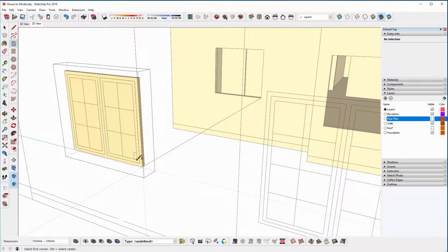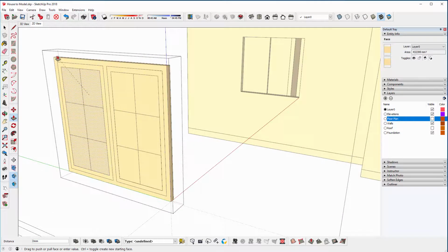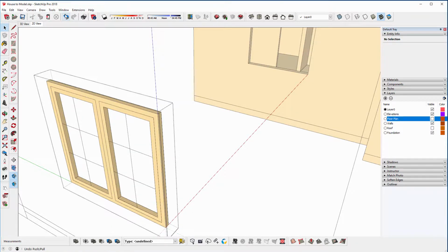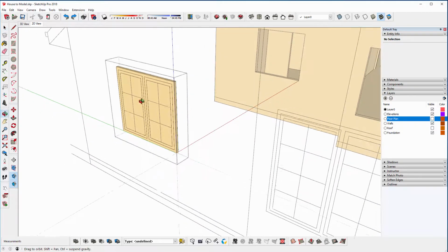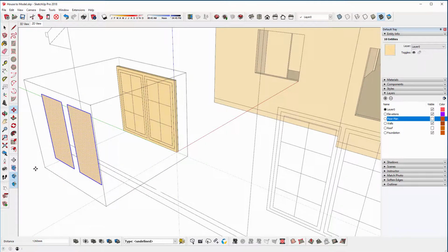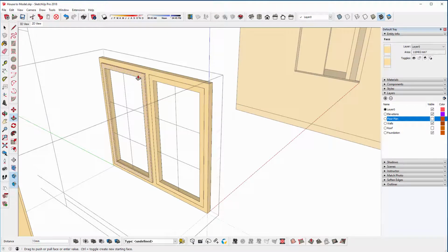So I'm literally using my elevations as a complete reference. So I'm just going to push pull that back and that one. And even, sorry, before you do that, we could make a copy of that surface. So I could select that surface and this surface, move tool and press Control to copy. Then I could push pull that back until it says on face. Double click to repeat the measurement. Push pull that maybe up 10 millimeters, and this one 10 millimeters.